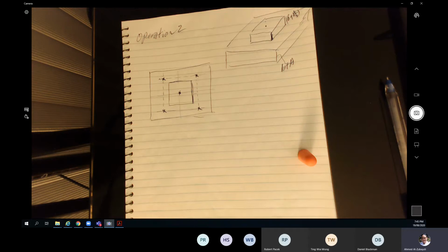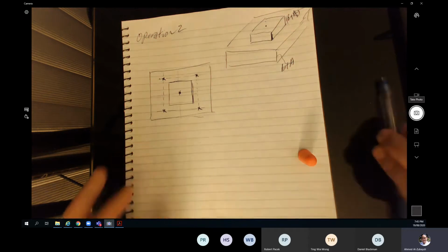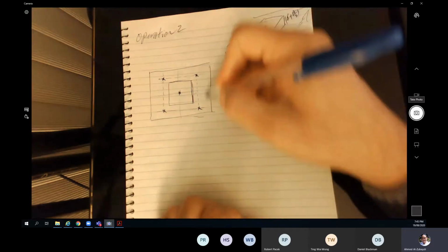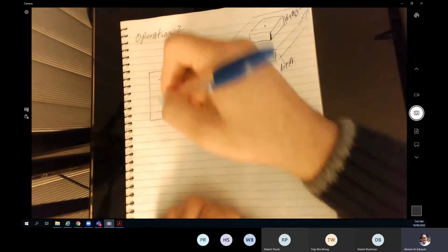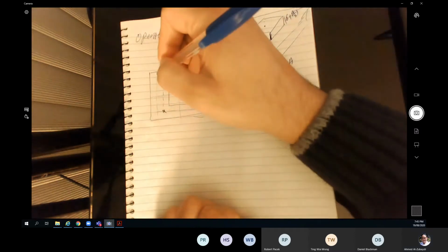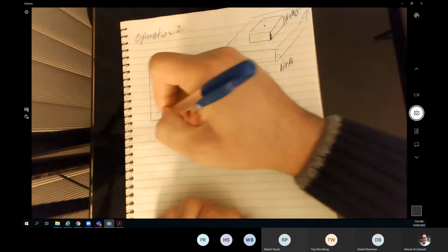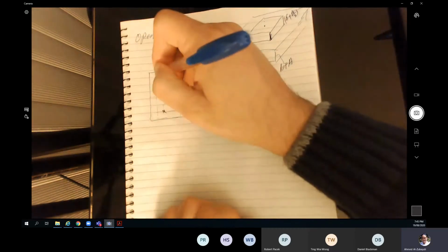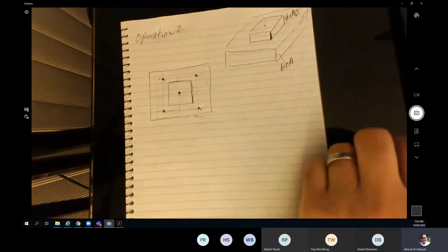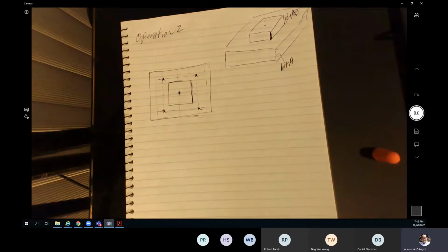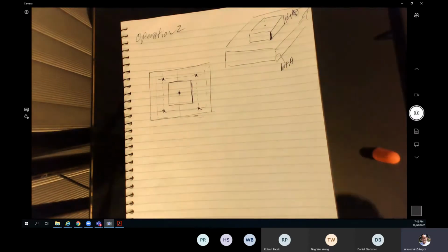Now the other thing is finding these 4 points. We want to extend the thing a little bit further to have the extra removal of the material. So as you can see, we're going to sketch another path, moving in this direction. So a new 4 points. These 4 points are going to be offset by 5 millimeter. Now, why 5 millimeter, not 6?